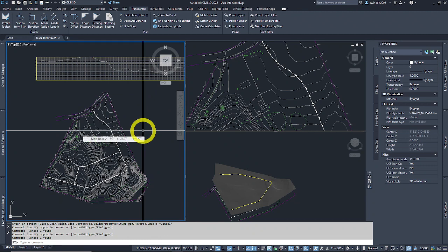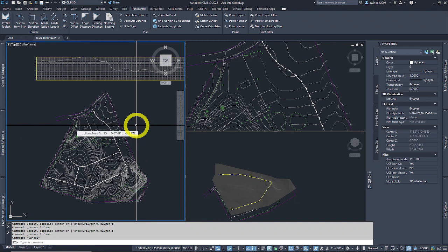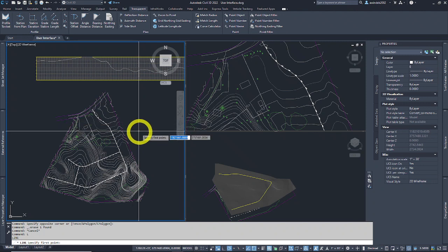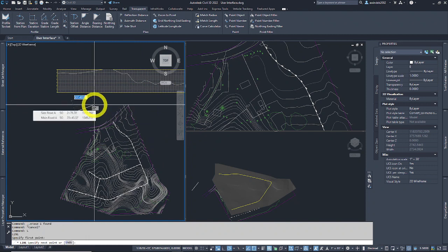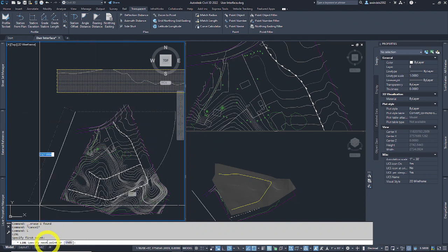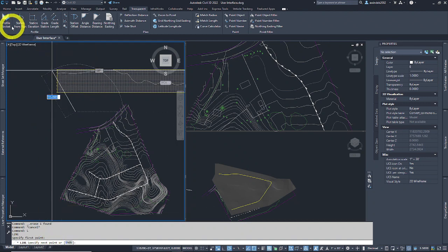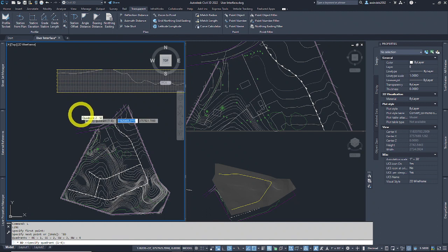Being a basic AutoCAD learner for this class might give you a little bit of a struggle, but we're mostly staying on Civil 3D commands. So with that being said, we're going to go back to page 14 and type in L for line. And I'm just going to pick a spot. Let's pick a point near wherever. It says the center of the screen. Then it's going to ask next point. Well, we're going to instead go to the next point. We're going to say we want it to draw that line by bearing and distance.